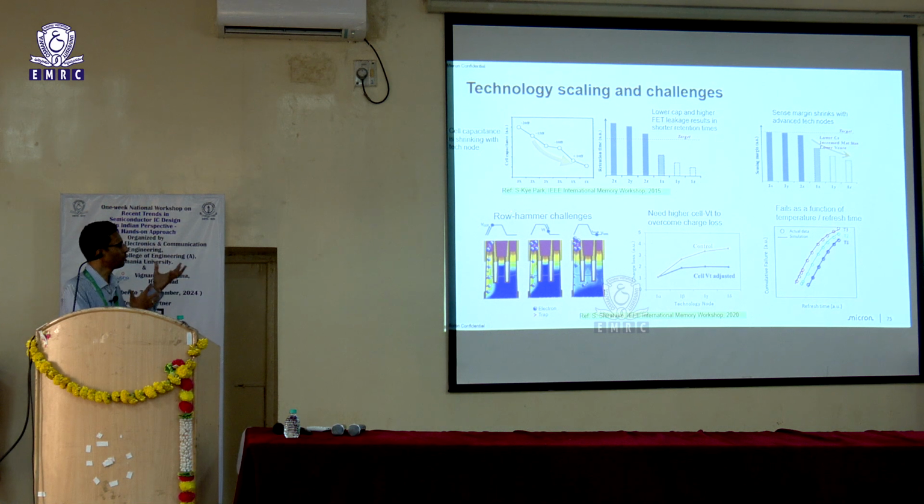So here we are talking about DRAM cell, which is 1T, 1C. So the transistor and cell capacitance are going to be shrunk. So what was 20 femtofarad earlier is going to be less than 10 femtofarad in 1X node, and at 1Y node it will be even further lower. So what does this translate to, right? You have a lower capacitance now, which essentially means when you are interfacing that with your digit line, there will be a lower voltage that gets developed onto your digit line.